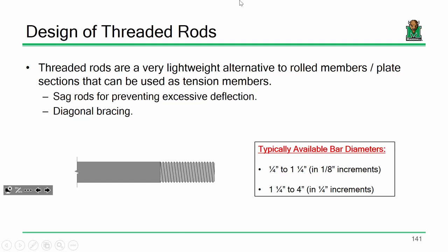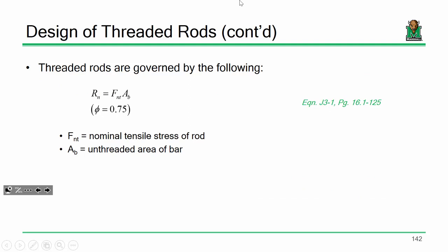It's pretty tough to find a 2 3/16 inch diameter round bar, but you could find 2 1/4 pretty easily. Okay, sound reasonable? So when we do our calculations, we'll get something like, I'll make up a number, a minimum bar diameter of 0.85 inches. We'll round it up and use something like a 7/8, just to keep it simple. That's sort of where that comes into play. We'll round up and use the next one. I'm fairly confident that if you calculate a bar diameter of 0.85 inches, you can go to a catalog and find the first one that'll work. So that one's pretty simple.